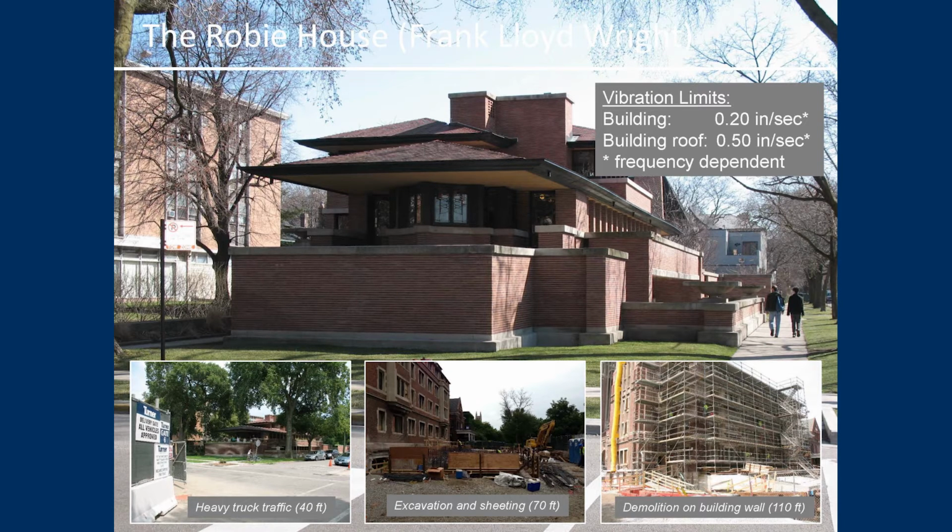0.2 inches per second was our limit. We knew there was some pre-existing damage. We also wanted to avoid human annoyance. Okay.